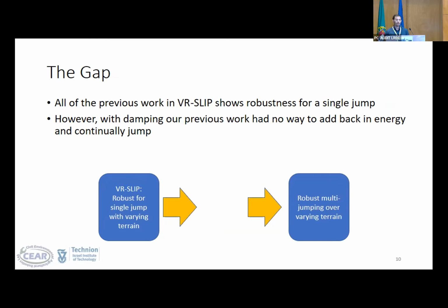And then we take all those parameters that we found before and do our simultaneous optimization, for constant forward velocity and YRL. In order to explore the effects of optimizing for YRL, we generated 3 different legs, each with a different hopping height, each with a Y initial equals YRL of 0.3, 0.35, 0.4, with an initial forward velocity of 0.8 meters per second, optimized for terrain variations of plus minus 0.05 meters. And then we took those legs and we pushed them past the optimized terrain variation, or rise, and ran them on terrain variations of plus minus 0.1, 0.2, 0.3, and 0.4.